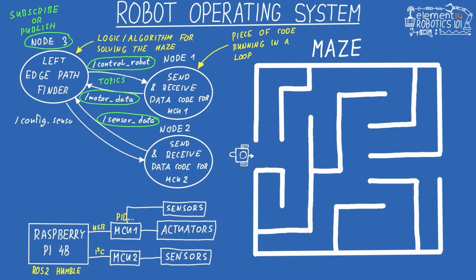For quick one-off commands like updating a parameter or reconfiguring a sensor, nodes can also communicate using a direct service call, rather than a continuous stream of topic data. Topics are expected to come at a certain rate continuously, while service calls are ad hoc and are also followed by a response. This response is extremely useful because in that way you can get a confirmation whether your service call has been successful or not, and also get some results back.